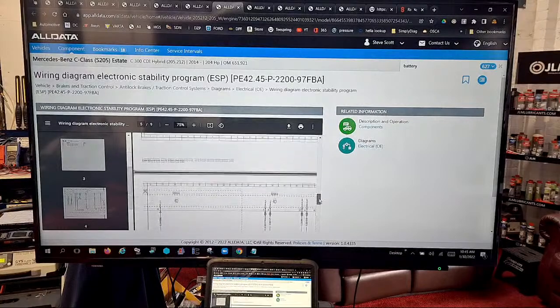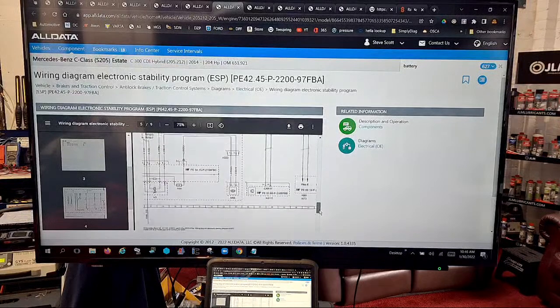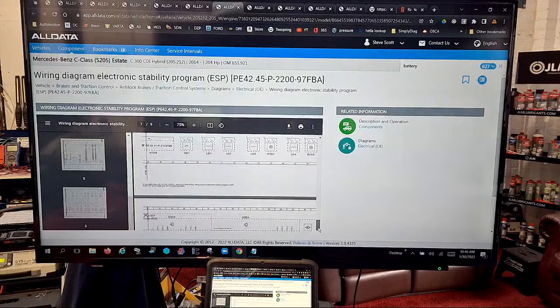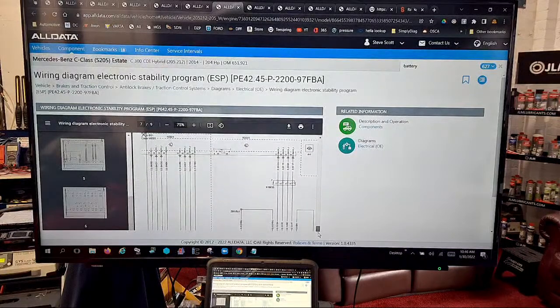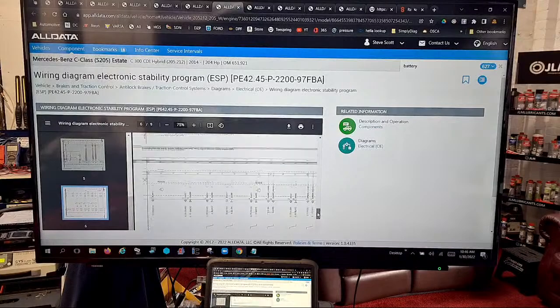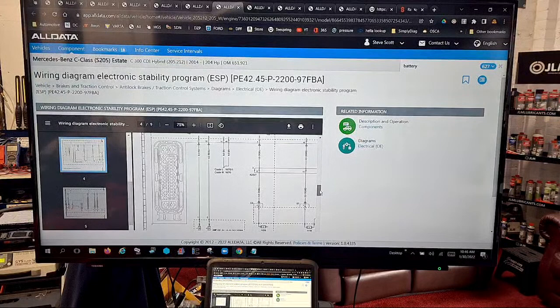And then as we work through the diagram, we can actually work out where our CAN lines are, if there's FlexRay on the vehicle. So like this has got FlexRay as well. So our communication lines, and then if we're looking for terminal 15 or auxiliary battery feeds and stuff like that, it's all there nice and plain. We can work through that. That gives us something to go at. And like I said, we've even got a pinout with our pin numbers.